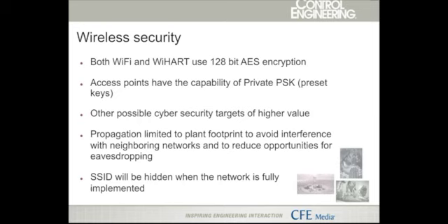Now, wireless security was something that came up. That was the other question: what does it cost, and can someone hack into the plant network and shut off pumps or dump chemicals? So these are pretty unfounded. Using good passwords, just typical 8-character passwords, would take someone probably somewhere between 15 and 20 years to crack with a brute force attack. But no one really is going to take the time because there are other targets of higher value. Usually a wastewater plant is not producing anything of great value.